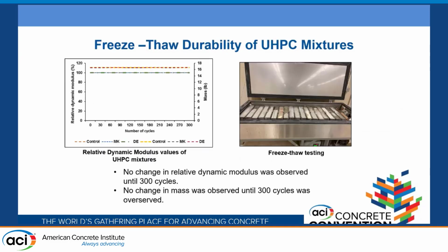These are the freeze-thaw durability results. We can see that there was no change observed in relative dynamic modulus, and no mass change was observed until 300 cycles.